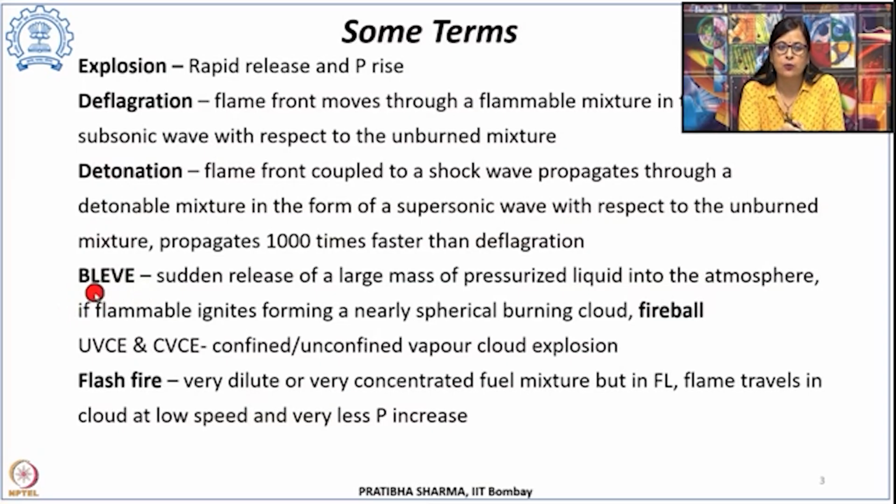BLEVE, that is boiling liquid expanding vapor explosion. This is a sudden release of a large mass of pressurized liquid into the atmosphere, which can lead to two incidents. It can be a fireball or it could be a flash fire. If the flammable mixture ignites and forms a spherical burning cloud, it is known as a fireball. It could be in a confined space or in an unconfined space, so accordingly it is an unconfined vapor cloud explosion or a confined vapor cloud explosion, depending upon whether it is a confined or unconfined release.